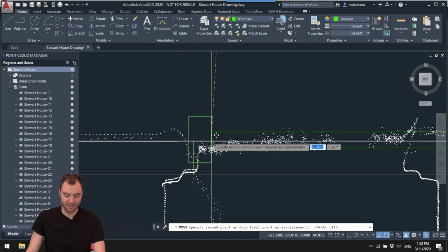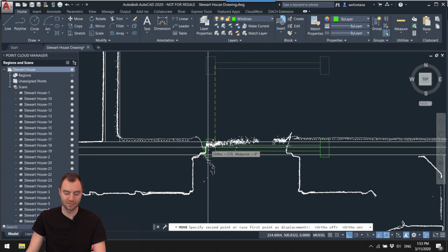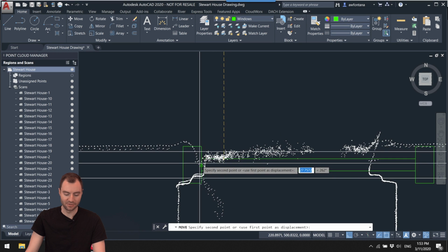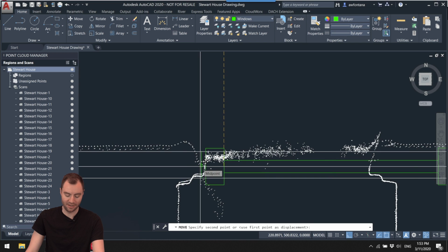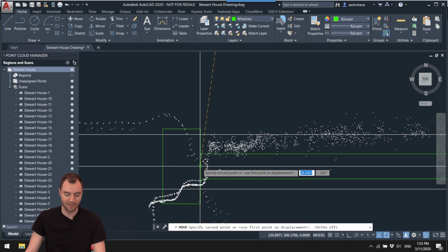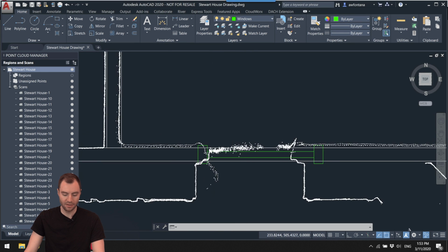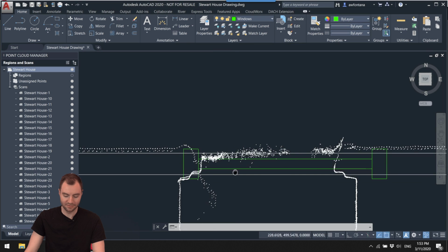And you can kind of see things start getting jumpy when it's in ortho mode, so it's trying to do ortho, but it's also trying to snap. So when that happens, I just hit F8, and then it turns ortho mode off. Okay, so you can see some of these windows don't fit at all.